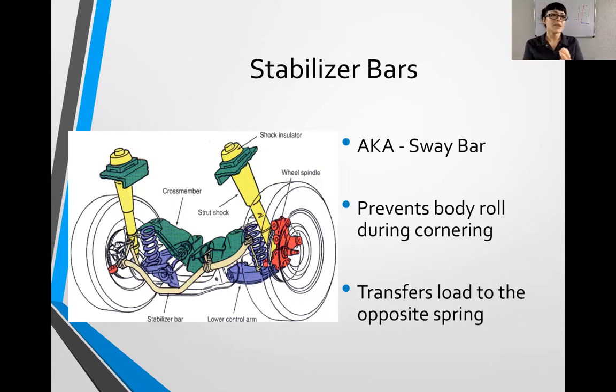Well, if I stiffen the crap out of both of those, I'm going to lose pretty much all my body roll, and there's a problem with that. Some of that body roll allows me to sort of dig into a corner and get traction. If I completely lose my body roll, then I don't get that, and I may lose control, and I am not going to be as fast, or I'm going to crash. So you don't want to do that.